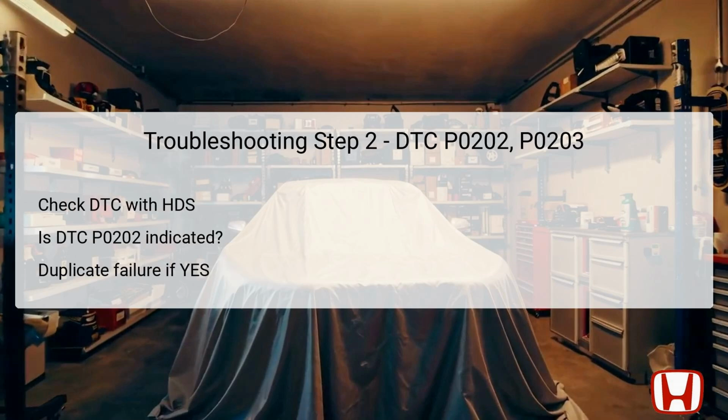In this step, after attempting to start the engine, use the HDS to check for any indicated DTCs. If DTC P0202 or P0203 is visible again, it confirms that the failure has duplicated, showing that the issue persists. Knowing this empowers the technician to proceed with further diagnostic procedures, aligning with manufacturer guidelines to address injector circuits thoroughly.